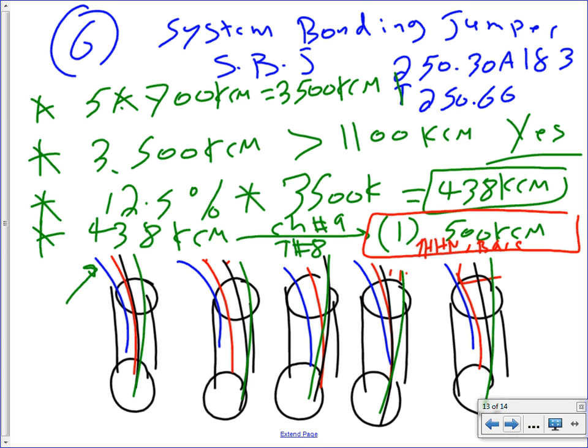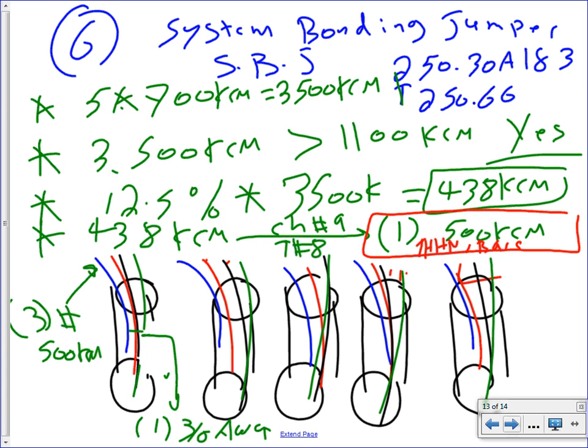Okay, so the last thing I want to show you guys right here, here are the 5 conduits you're looking at. Now the conductors will be 3 conductors, 500 kcm, and the neutral conductor, we screwed up here. The neutral conductor would be one conductor. What was the size of the neutral that we came up with? 3 aught AWG. Are you sure it's 3 aught? No, 400 kcm. Thank you. That sounds small. So one conductor, 400 kcm. Can you see, guys?